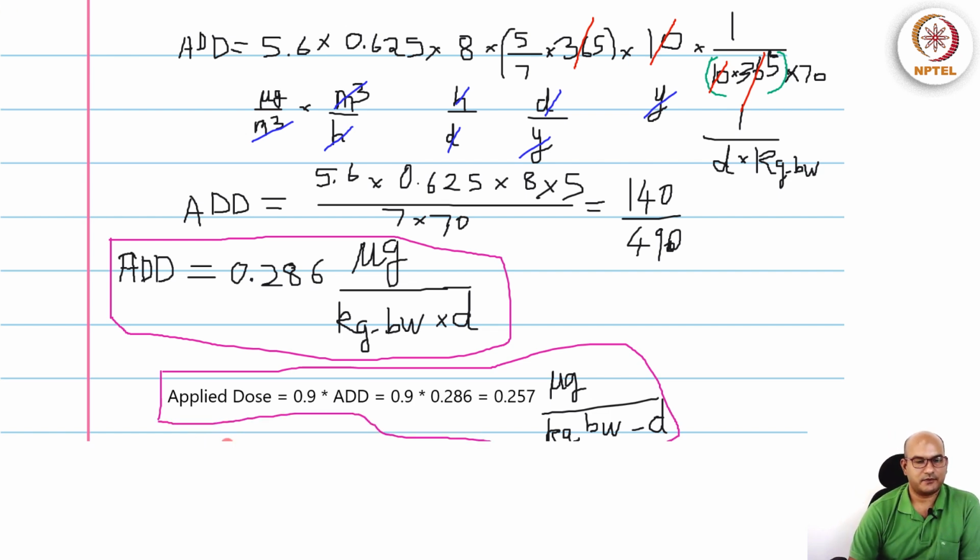So in this way we have seen how, if we are given the release rates from emissions, we do the calculation up to the exposure. This is a simple example where we knew the emission rate and the characteristics of the air exchange. From that we calculated the expected concentration in the room.